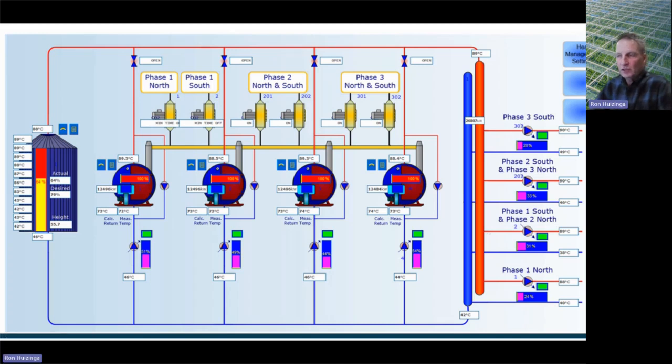Of course, your plants only need CO2 during the day. So from your CO2 start time to your CO2 stop time is basically when you would want to run your boilers. In many cases, for a customer with a buffer tank, the boilers will start up in the morning when the CO2 starts, then run all day long. And then at the end of the day, they shut off, and they don't run all night long.